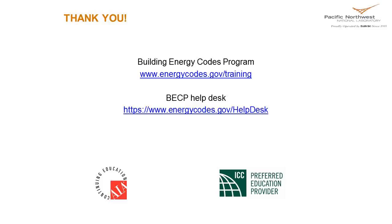have 2 separate compliance reports. I'm going to have a compliance report for the addition and one for the alteration. Those are 2 different ways COMcheck is calculating compliance. Alterations are very assembly specific and compliance specific, meaning each assembly has to meet code individually. Where additions, you got a little bit of trade-offs you can do. So again, show 2 separate reports.